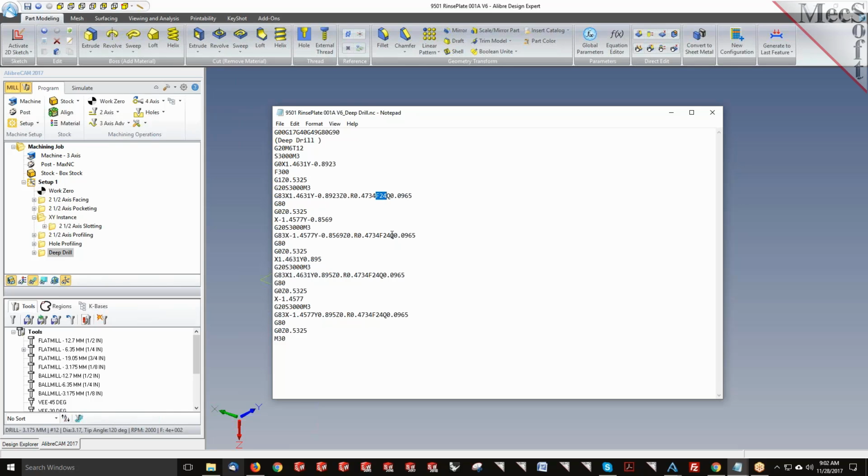Could you save custom peck drill settings? One thing that's really critical to us is we do a lot of drilling and peck cycles. Let's say we've got a part with 1,000 holes in it. We tailor each of those feed rates, the Q value and that feed rate you've got highlighted there, pretty specifically to each part.